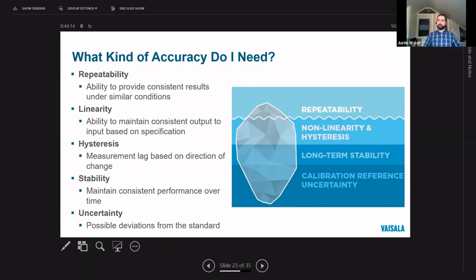And uncertainty. This refers to the quality of the measurement, the reference instruments, and their calibrations to accepted standards. This will dictate the overall quality of your calibration. Of course, it is ideal if these characteristics are known for the instruments you use.